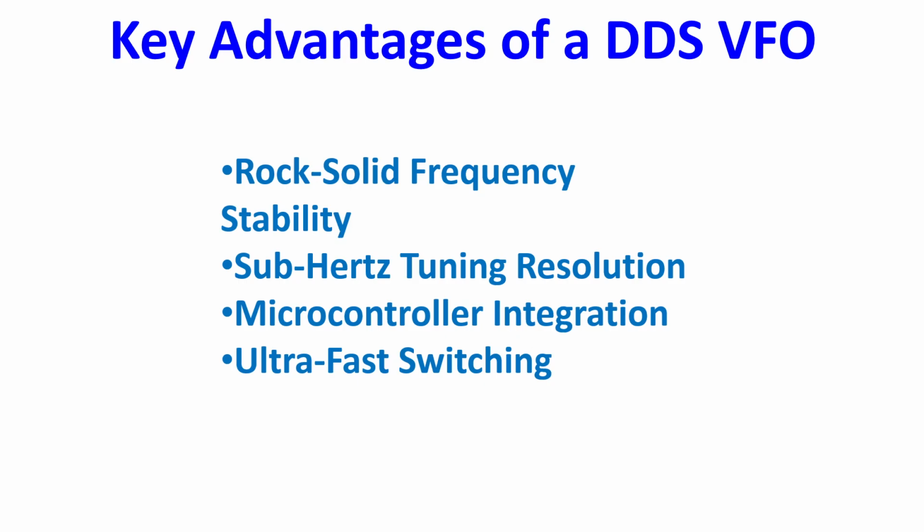Microcontroller integration. Because the frequency is controlled by a digital word, it interfaces seamlessly with microcontrollers. This easily unlocks features like digital dual VFOs, split operation, programmable memory channels, and electronic frequency displays. Ultra-fast switching. A DDS can jump from one frequency to an entirely different band almost instantaneously, making it highly agile.